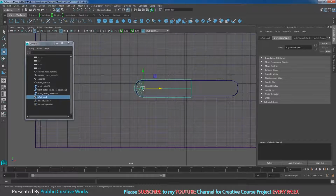So I want to keep my pivot on this vertex. So hold D on your keyboard. So click on this vertex. So that means our pivot will be changed to here. So now press Ctrl D to duplicate.